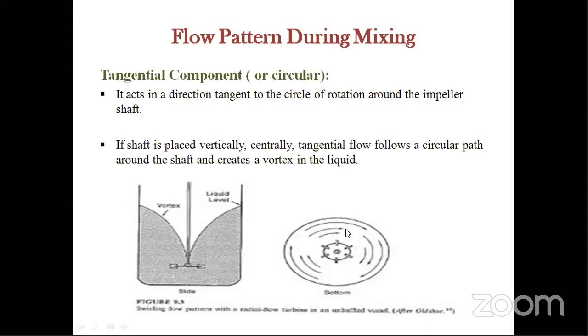Okay, when the vortex is formed, first, when you mix these types of material in a less viscous medium, you have to maintain the mixing speed. If you maintain an optimized mixing speed during the mixing process, the vortex is not formed. Okay, if your mixing speed increases, the circular motion or circular components are directly converted into vortex mechanisms, and this reduces your mixing, and uniform mixing is not achieved by this vortex mixing process.